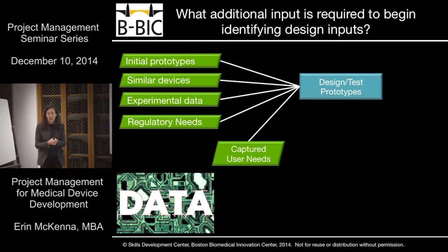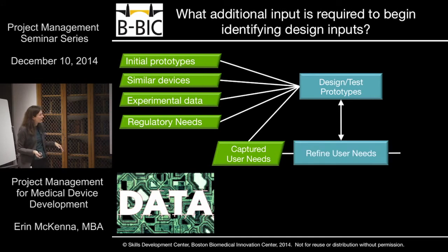For instance, if your product has a Luer lock on it, there are a ton of ISO standards related to what kind of Luer lock. It's more recently connected to what function because of issues in the past with the fact that Luer locks used to be universal, so you could accidentally connect somebody's feeding tube to a blood catheter. So now you actually are thinking about, okay, what function do I need? What size Luer lock? What are the applicable standards that I'm going to need to start thinking about so that I'm designing prototypes that would respond to the clinical use need appropriately? So you consider all of those elements.